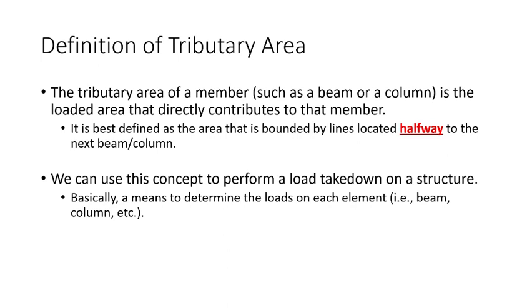Sorry. So, tributary area is something that we've dabbled with a little bit. It is the area that directly contributes to the load on a given member. Tributary area is best defined as the area that's bounded by the lines halfway to the adjacent beam and column. And the method that I'm going to show you is going to work for 90% of all the building systems that you're going to be dealing with as a structural engineer, and even bridge systems as well. There are a couple scenarios where what I'm showing you today isn't really going to work.